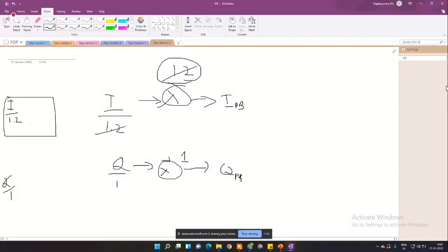Now, how do they know that it's actually 1.2? They check all of the IQ impairments. For example, let's say I am supposed to check gain. They run it across all operating frequencies, starting at 70 megahertz up until 6 gigahertz, which is their operating range. For this entire range, they map out the change in the gain that the mixer gives, and then accordingly they program their IQ impairment code to behave in such a way that everything is nullified.